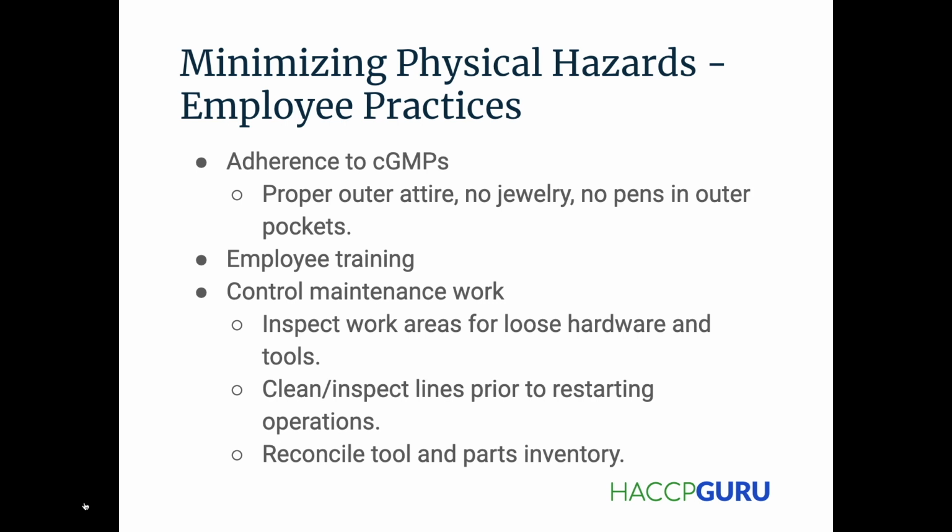Quite a few experiences I've had where maintenance came in on the weekend, did some work on a line, and then left because in their mind they completed their work. Then an operations employee comes in and says, well, maintenance did their work, I'm sure they cleaned up. And then you've got shavings inside the product line.